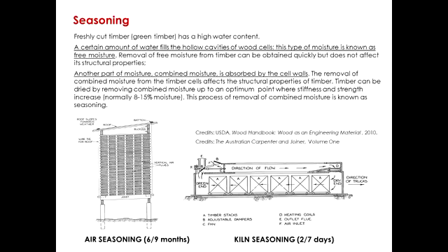the timber boards, you stack them, and you leave them there for 6 months, 8 months, up to 9 months, and eventually they'll season, they'll lose that extra moisture content. You need a lot of space to do that. You also need to wait for a lot of time. That's why kiln seasoning is a process that is much faster, so we're talking about something that will happen between 2 and 7 days, and that allows you to control the temperature and humidity within the kiln to make sure that you lose the right amount of moisture in a very short period of time.